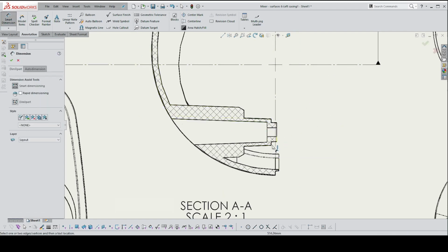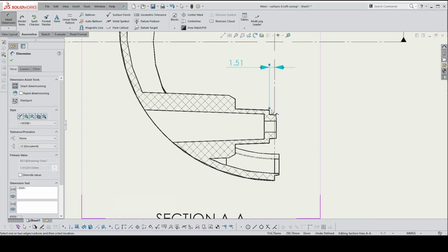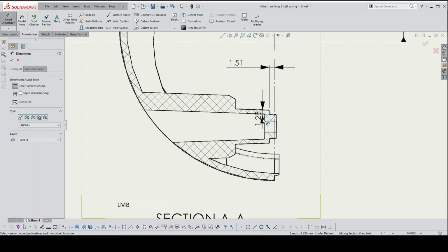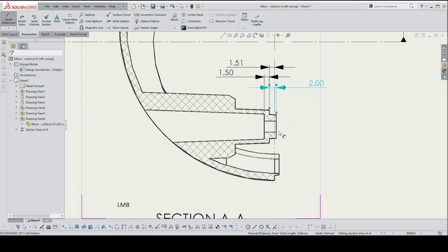So let's do that. So I'm going to go from my datum down to this line. That line is my subdatum or secondary datum for a good reason, because that's the plane which will meet the screw boss on the other side. So that's the point from which I want to determine what the gap is between these two. So I'm going to then use that one there. So we won't get into secondary datums at the moment, just understand that they exist and they're legitimate to use. So I'm going to use that to determine the heights of this item.